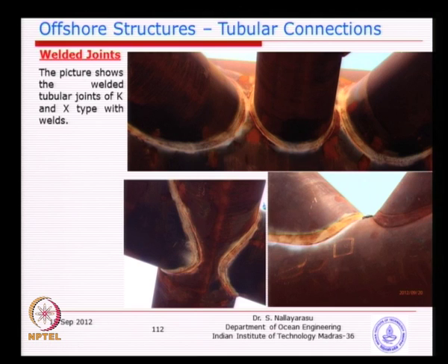So, basically incorporating these effects, because when you are fabricating this joint for model testing, you will include these weld effects, any undercuts basically at the location of the junction between the parent material and the weld, you may see some kind of undercut or maybe a defect.